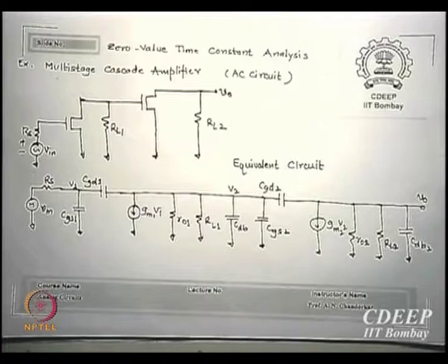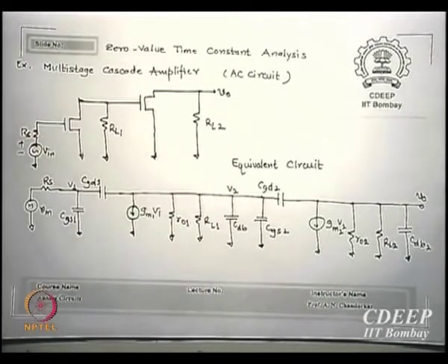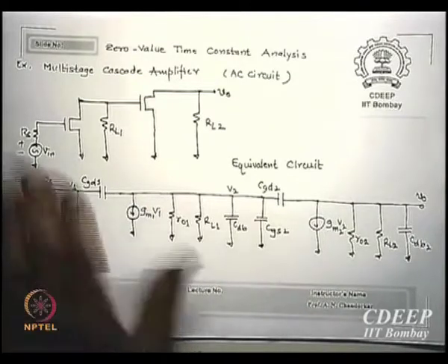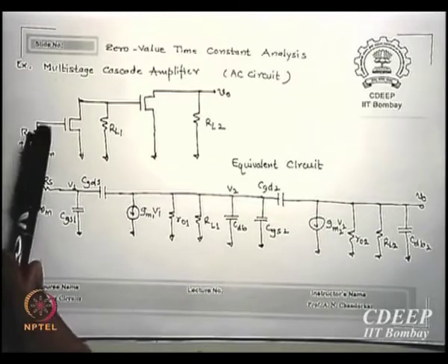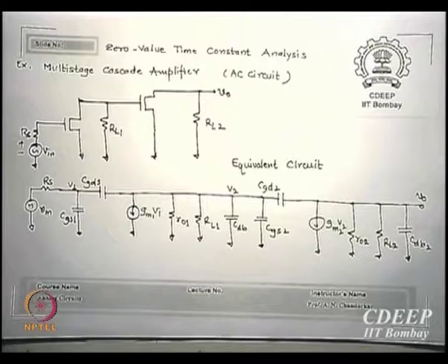What I have not shown here is the DC biasing part. Though it may exist, RG may exist, and the supply would have an RG1, RG2 kind of arrangement, right now only the AC equivalent circuit has been shown. We also neglect CC1, CC2 and the CS bypass, the RE bypass and RS circuit. Why are we neglecting that? Because right now we assume they are not part of the external circuit. This is a simple analysis to show how to get it. In real life there may be CC1 here, CC2 here, and everywhere things will appear as they should.